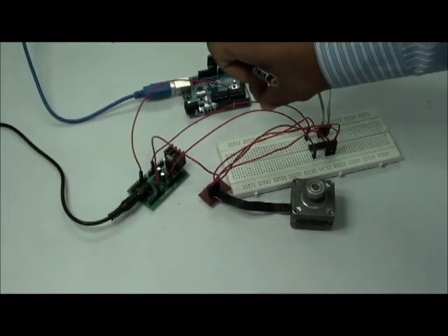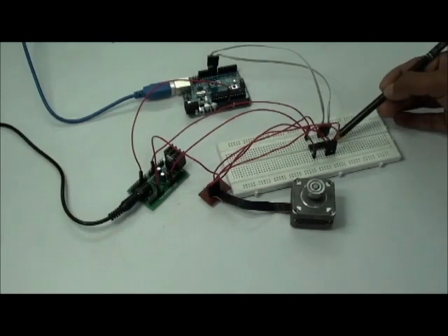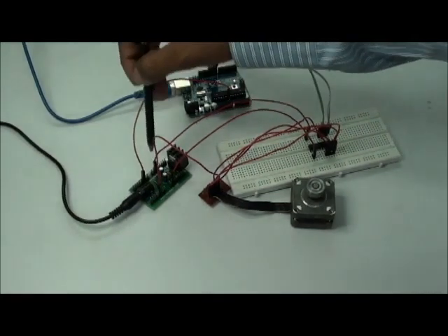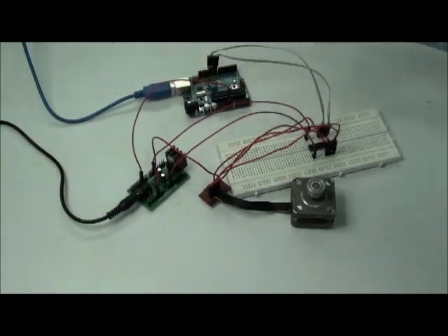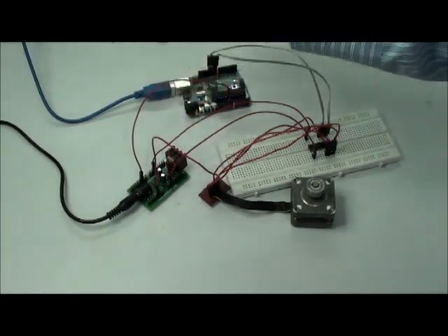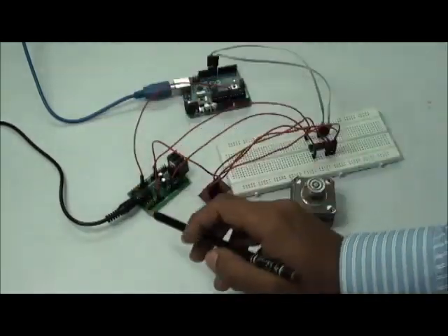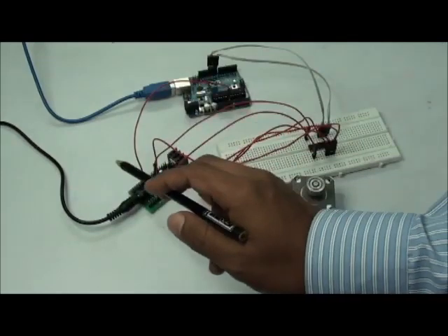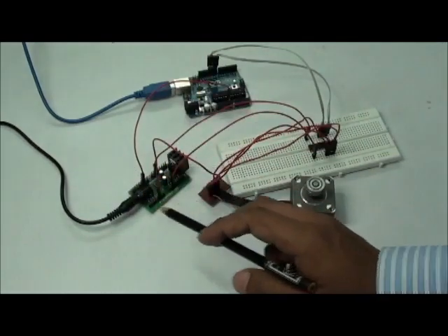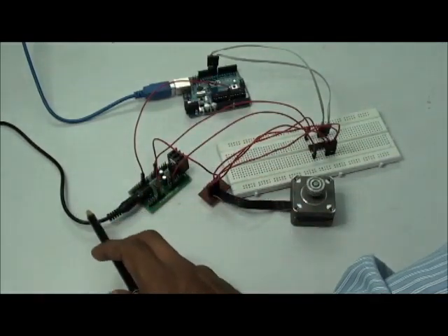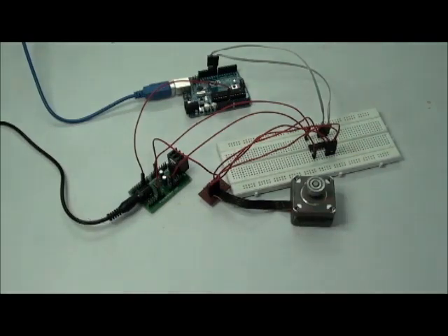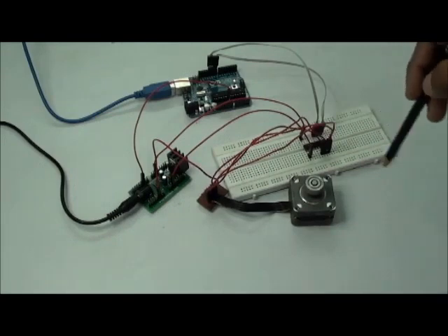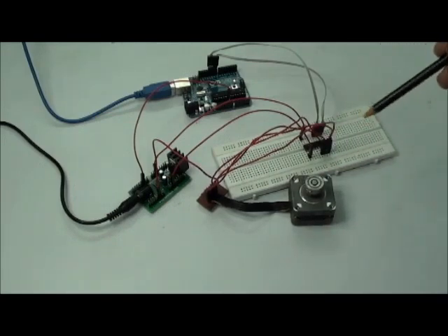As I told, here is the notch, and here are the input pins. Pin number 8 is grounded, and pin number 9 is connected to the supply. And this is my small PCB power supply breakout, which is available in our Tenet house, which gives normal 12 volts and 5 volts output. If you input the supply, a 12 volt adapter, to it, this is how it works. The motor is just rotating in the anti-clockwise direction.